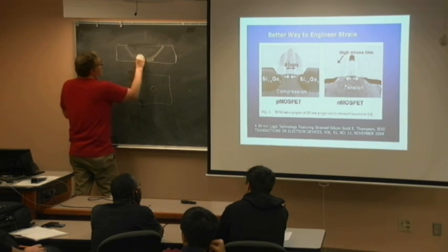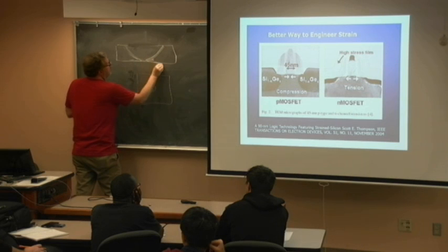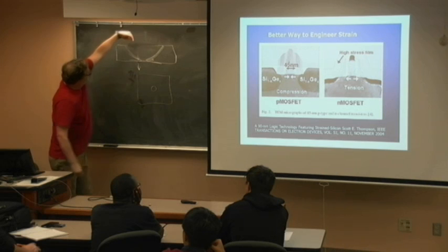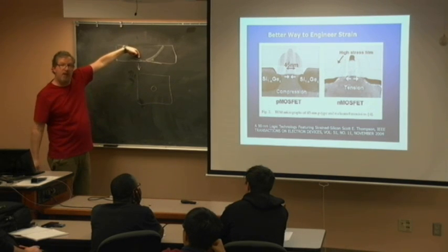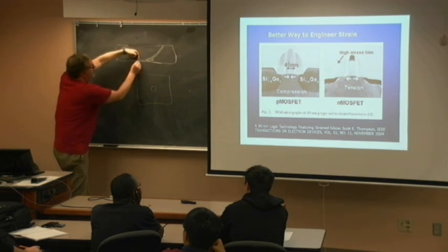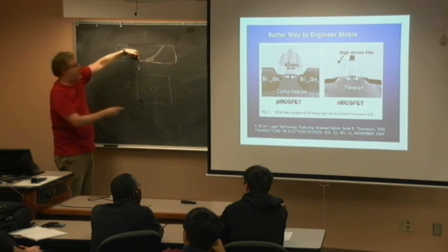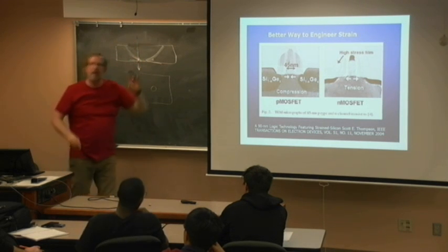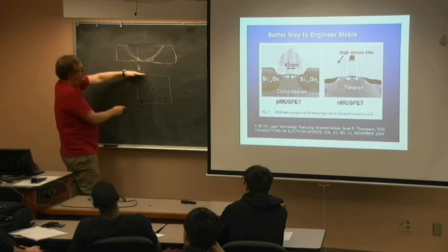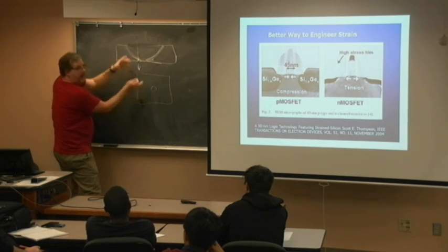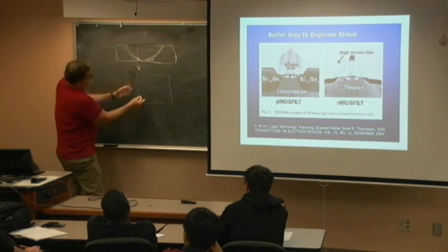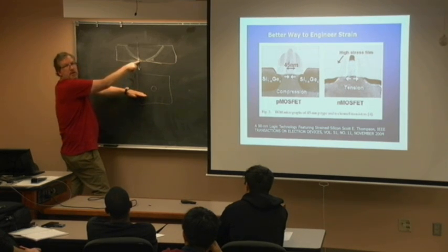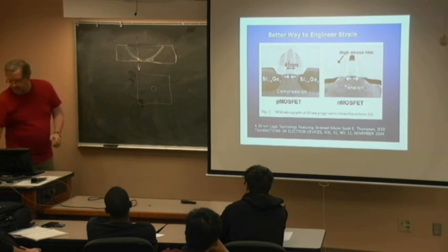Right here, this becomes so thin, it's electron transparent. So I send my electron beam through this very transparent region, and the transistor's sitting right there. You have to kind of know what you're doing, so you put the transistor right there. I send my electron beam through there. I am going to get a Fourier transform of that, and then below that, in my electron column, my electron microscope, I'm going to get another image plane where I can actually see that transistor. So if that didn't make sense to you before, hopefully it does now.